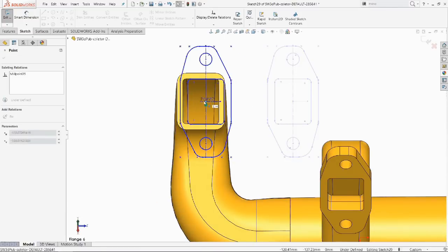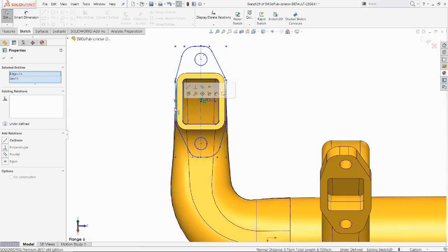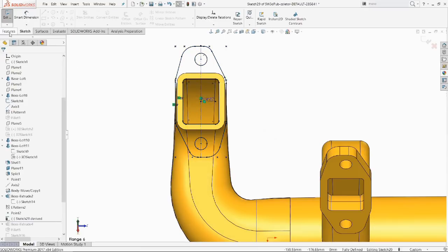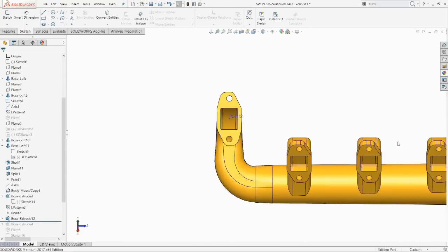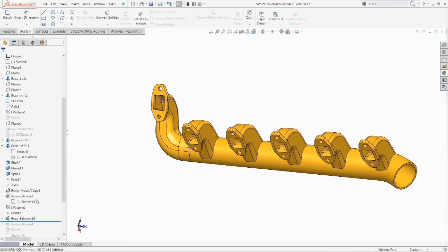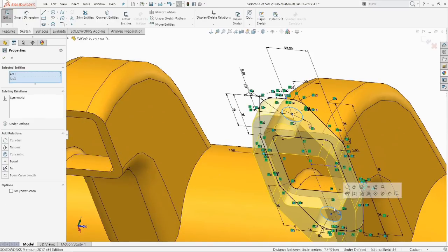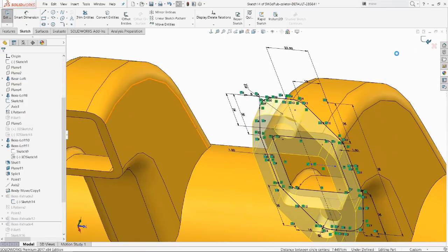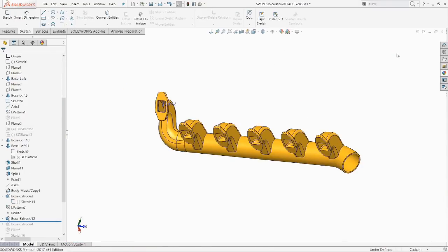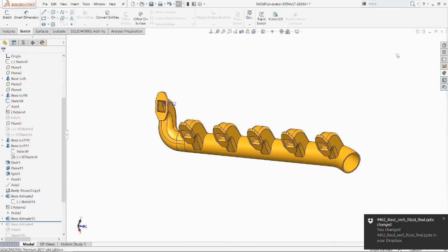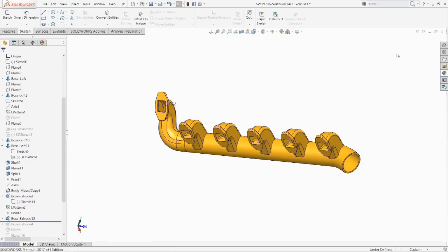Here's this. Notice I don't have any sketch tools open. I'm in a sketch right now. I don't have any tools available to me. All I have are the options to locate it. And now if that original base flange changes, the derived sketch will also change. Right? Like here. I'm going to get rid of those circles here. Let's take a look at this. There, my derived sketch has also changed. So it's not just copy and paste. Okay? It's pretty cool. So the way to get to that is you first pick the sketch that you want to create the copy of, and then the face where you want this to be, and then derive sketch from the drop-down menu. Okay?